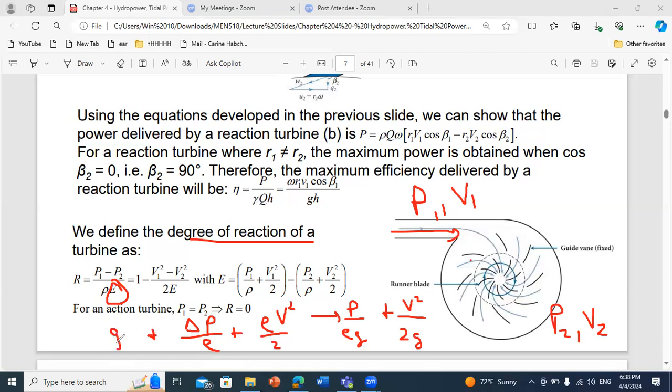If you write your terms in this way, then you have the corresponding unit, which is energy per unit mass, because if you multiply all of the terms by m, mgz is the potential energy, it's in joules. So whenever you divide by m, all of your terms are in joules per kilogram. So now when I divide delta P over rho by the energy extracted per kilogram from my turbine, I can get what is the fraction of energy that I'm getting due to pressure drop.